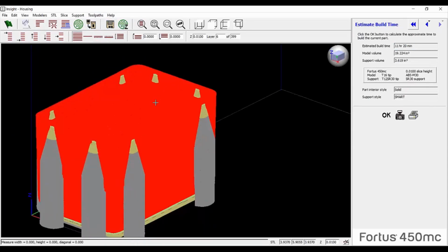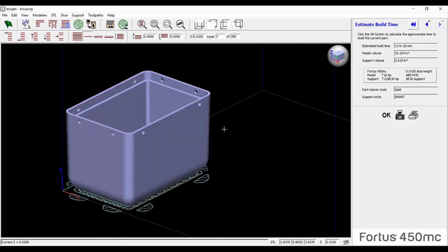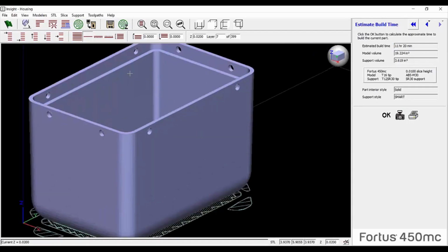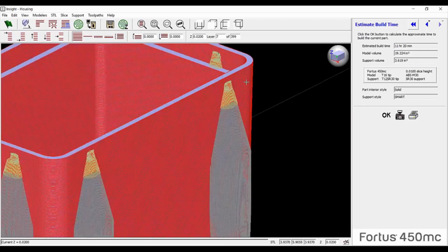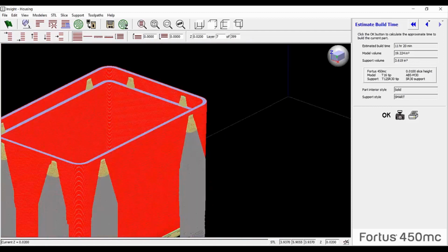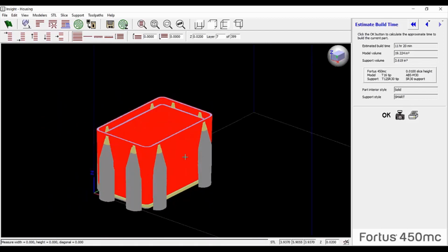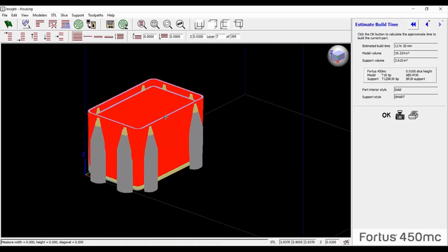And the problem here is we have these little holes at the top. Let me turn my STL display on. These tiny little holes right there, and what's happening is the support structure is starting there and originating, and it kind of grows beyond its periphery and then cascades all the way down the whole side of the part. And with 8 holes or whatever this has, that obviously equates to quite a bit of support and quite a bit of time to deposit it all.